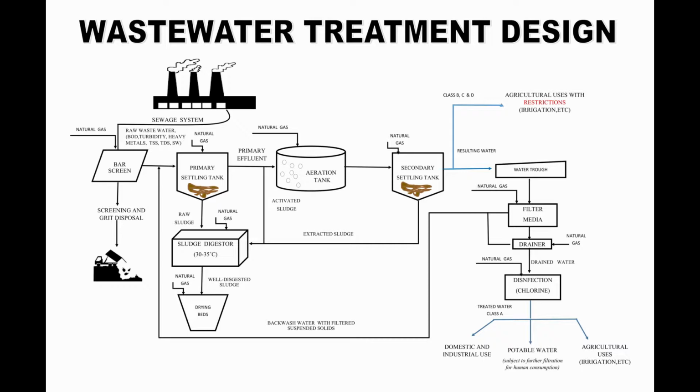The secondary treatment begins when the primary effluent goes to an aeration tank. The biological process takes place here, where a liquid is held in order to increase the amount of air within it, at which the high oxygen levels increase the speed, and then the water is cleaned.